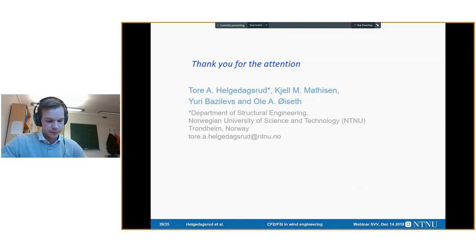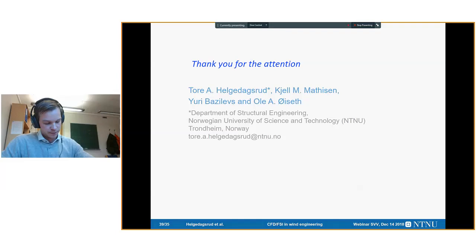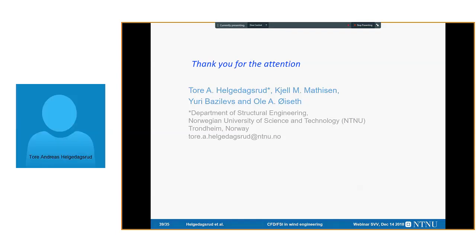Yeah. Thank you. I may have missed the beginning part of your presentation, so I would like to know whether you did any modification to the LES model or the boundary conditions. Okay, so we don't do any special treatment of the boundary conditions other than using this penalty formulation for the weakly enforced no slip. Otherwise we strongly prescribe the velocity. It's also the same for the turbulence. So it's just standard boundary conditions, really.